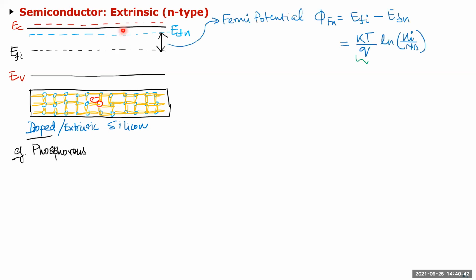So phosphorus is obviously one which people use. Phosphorus gas is passed for diffusion to create an N-type material. For example, if you want to make an N-well, like yesterday I was showing you, you take the mask, you do a cut on the mask, you raise it to a really high temperature, pass phosphorus gas, and it will diffuse in that mask area and create an N-well.